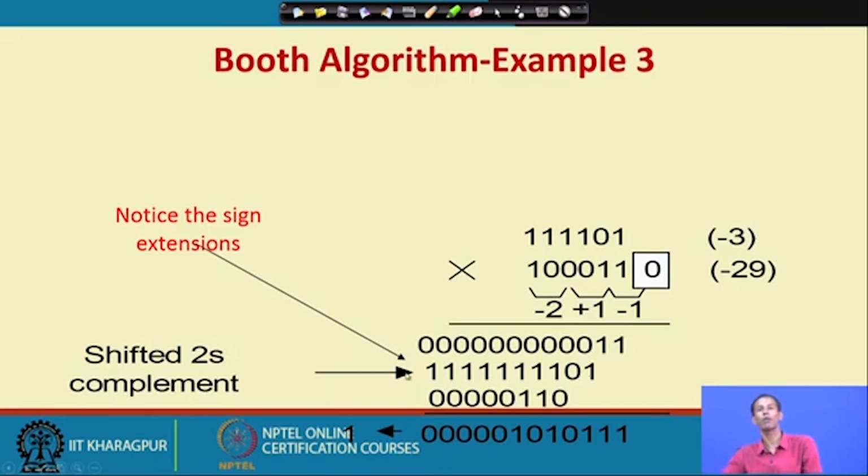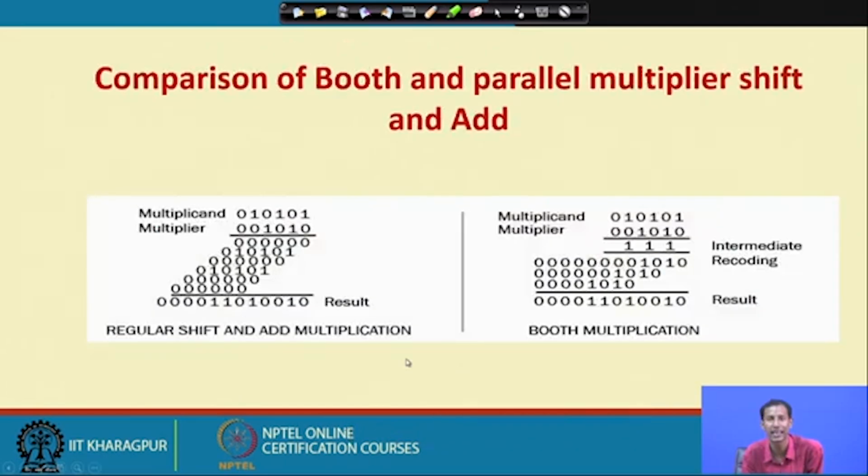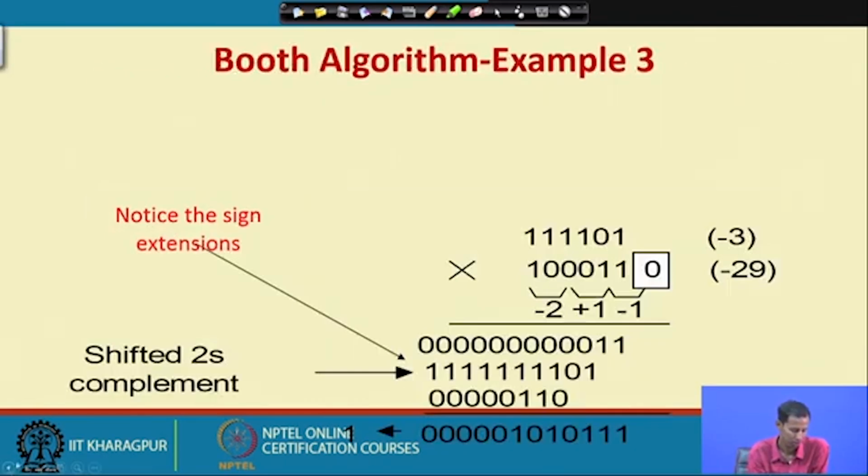Then what is the problem here? Is there any problem? Yes, obviously there is a problem. As I am increasing the sign bit for this particular partial product, that means I am increasing the full adder cells, whenever I use this to add these particular bits using a Wallace tree or any other addition operation.